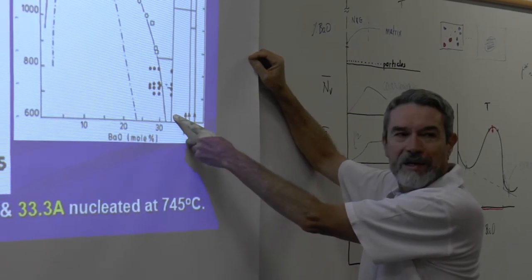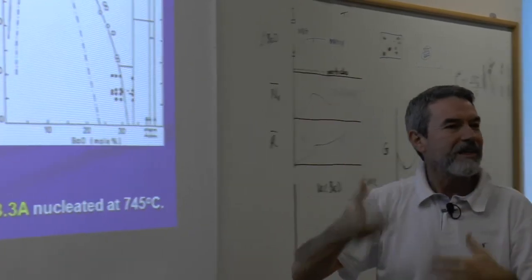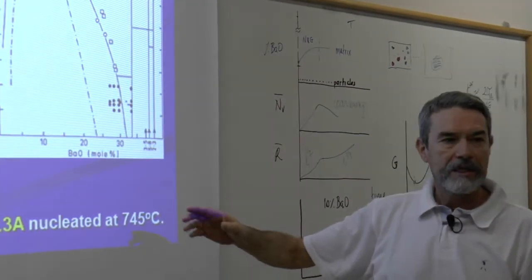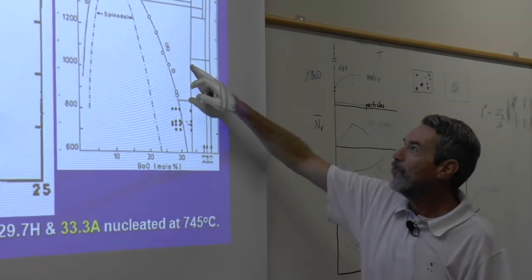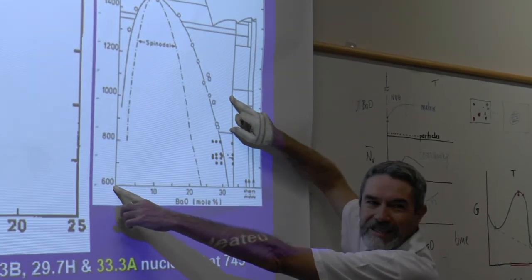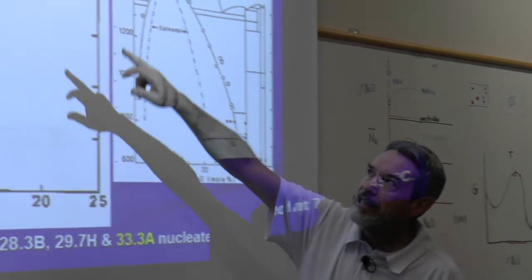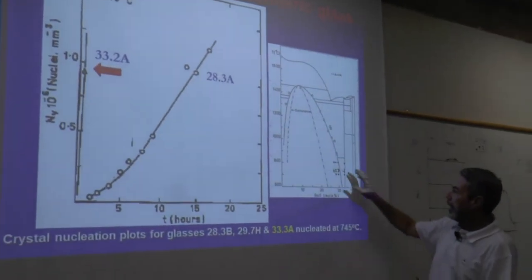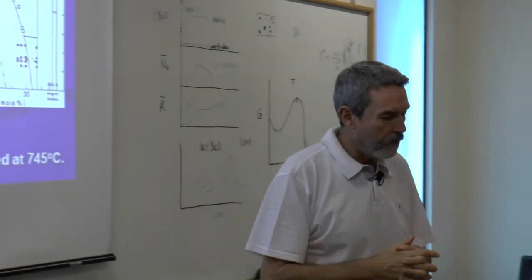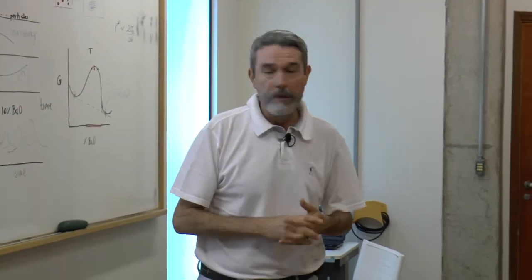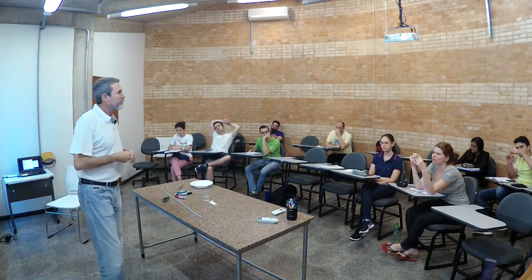So if you come here, then you have nucleation of 2 phases, which may or may not be higher than the other one. In this region here, you have only this phase, and maybe silica. The other phase will be silica, but silica is so viscous that it doesn't appear at this range of low temperatures. So I'm working in a range where barium disilicate is the only phase. But here it is unpredictable. It can be higher or lower. It depends on the interaction of two phases.